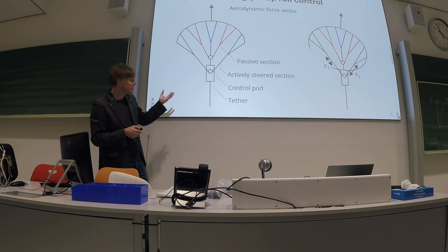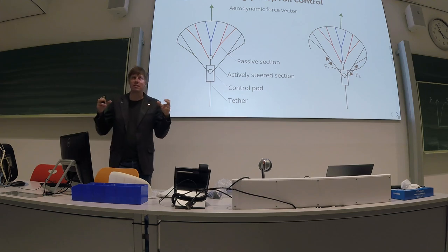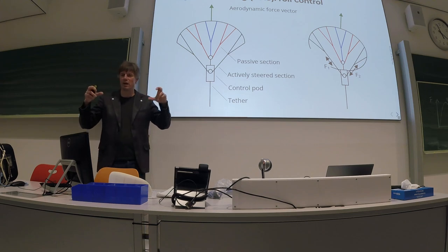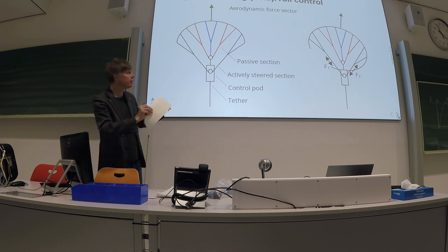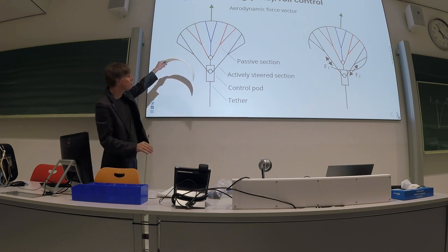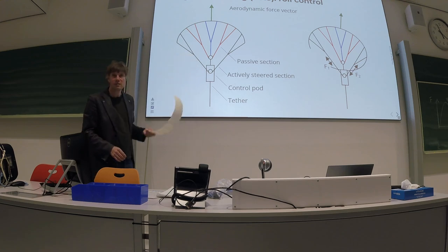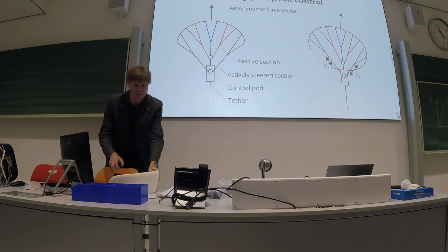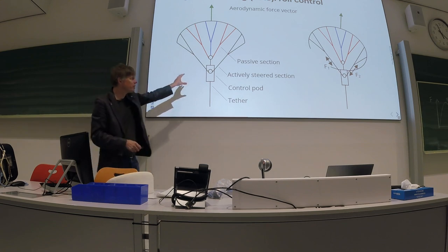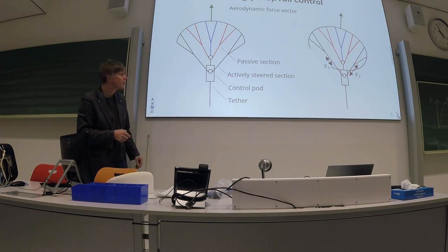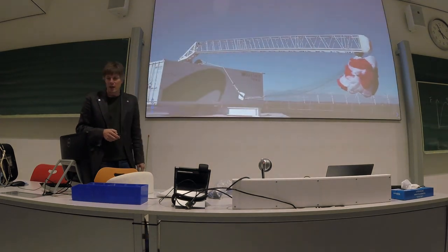What SkySails can also do, since a year or 1.5, is pitch rotate the entire wing. So they can not only roll it, but they can also change the pitch. For this they use a second mini winch within the control unit.